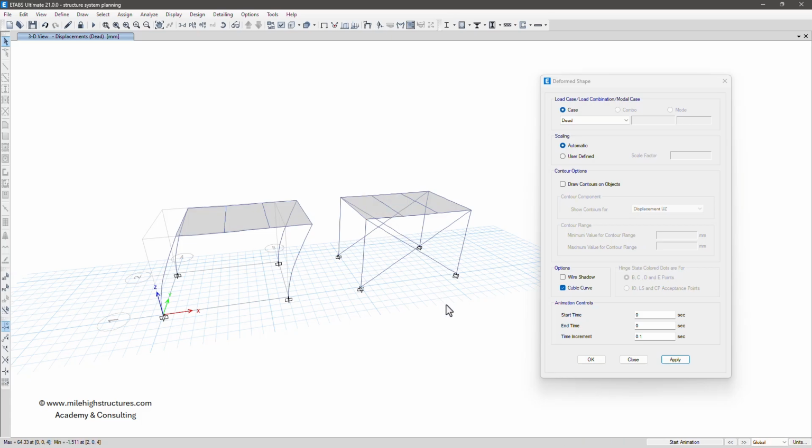That is the purpose of the bracing. It is always recommended that, as this is a shear connected frame, in the shear connected frame only we should provide the bracing. In a moment frame it is already stronger. It is not that the moment frame needs bracing, although it never harms to provide bracing in the moment frame also, but it blocks the access inside the structure. So as I said, it is always recommended to add bracing in the shear connected frame.